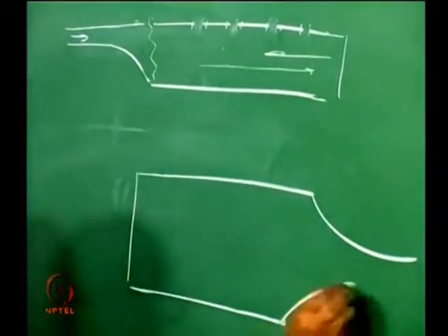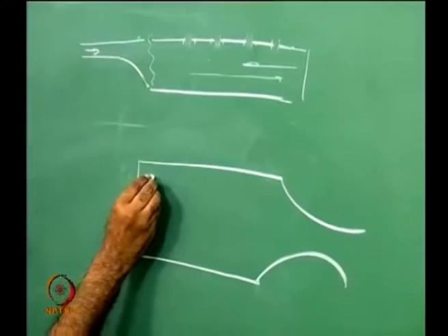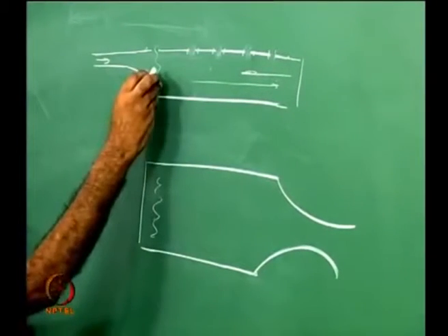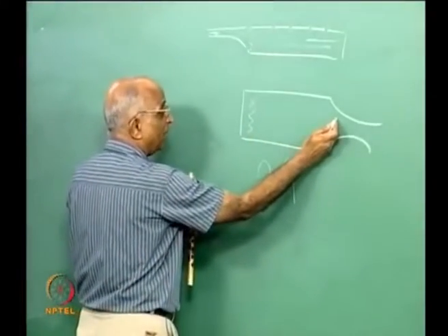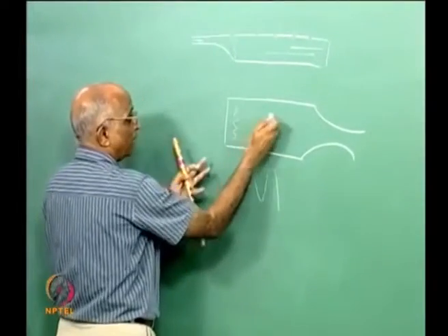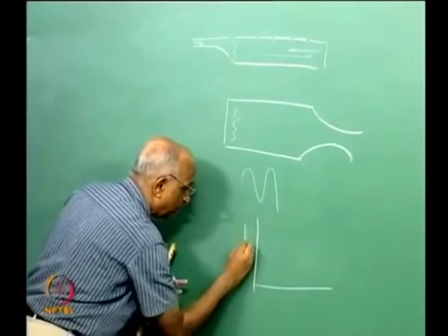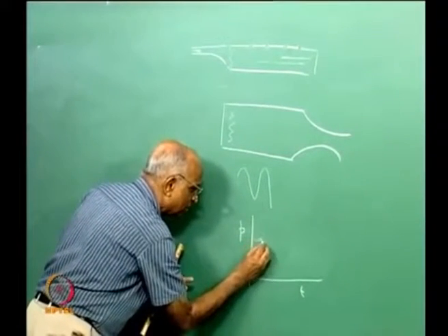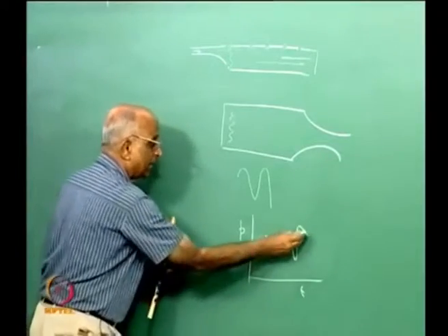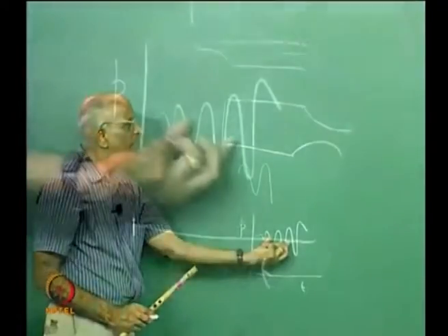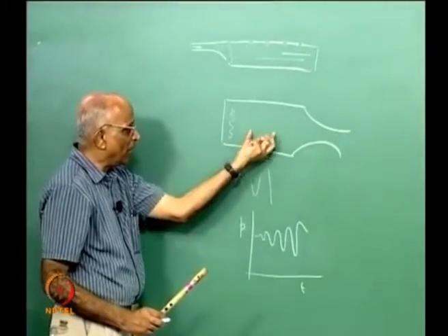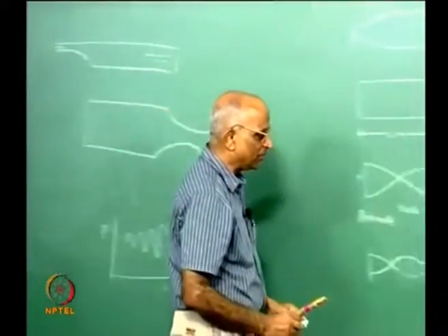And this is essentially what is happening in a rocket chamber also when I have an instability problem. I have the chamber like this, I have the nozzle over here, maybe I could get combustion taking place here, the combustion interacts with the pressure mode here, increasing my amplitude of pressure at this point, and the whole standing wave amplitude increases, and therefore my pressure increases. Maybe with respect to pressure and time, I start here with small oscillations, it grows faster and it creates a problem for me, I end up with very high pressure. And this is what we mean by combustion instability, and combustion instability happens in the standing wave mode, and it is known as the wave mode of combustion instability.